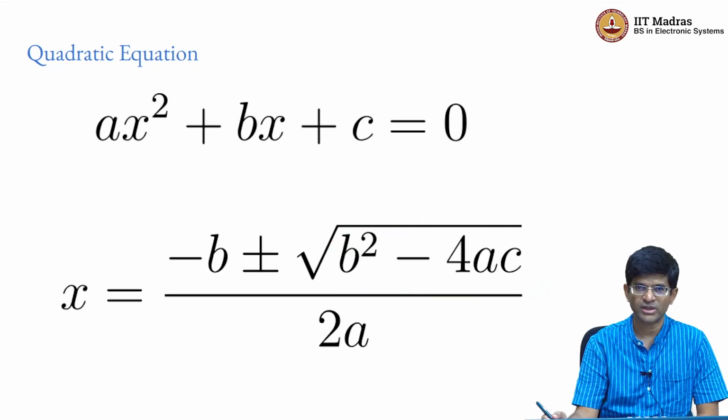Part of the reason why I am focusing on the discriminant is that this particular operation, the square root, is something that's a little tricky to implement in hardware. It can be done. There are reasonably efficient implementations that are directly in hardware and can potentially even be done using some kind of a combinational circuit, but they are definitely a bit more advanced than what you would expect in just adders and multipliers, right. So I'm going to focus for now on the discriminant, and as long as we can figure out how to take care of the square root, it's actually not too hard to do the rest of it either, right, but we are going to leave that aside for now.